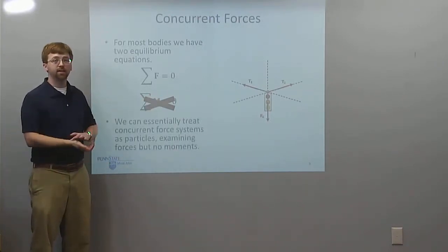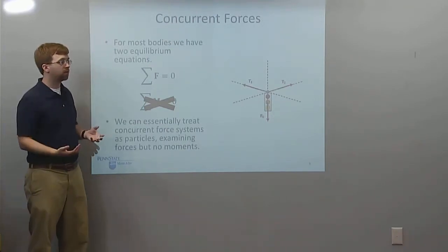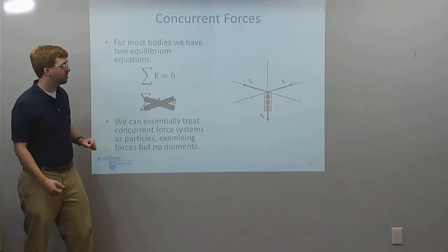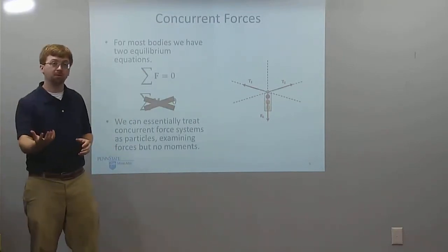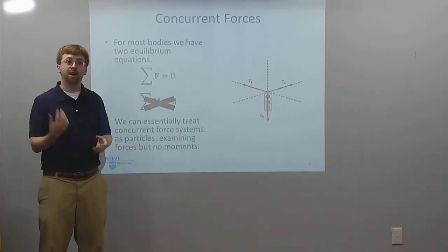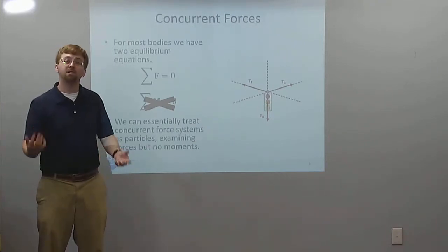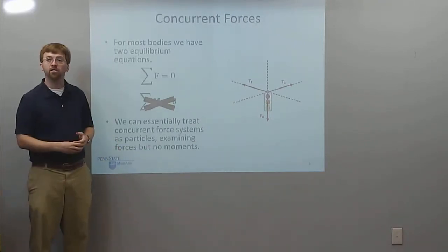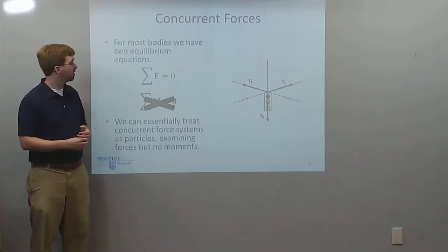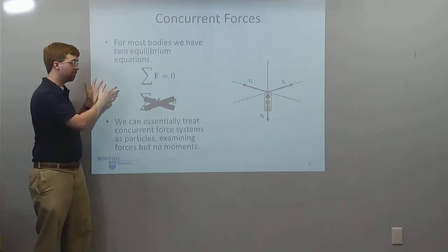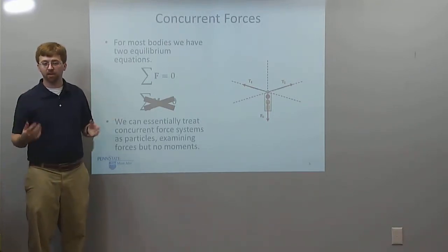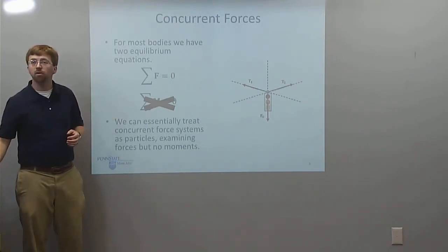So we can essentially treat this as a particle, and in particle analysis we only deal with forces, we don't deal with moments. So there are no real particles, but the approximation of concurrent force systems as particles is what really constitutes particle analysis. So with that, we only deal with forces. If we're dealing with any of the moments, then we're dealing with something that is not a concurrent force system.